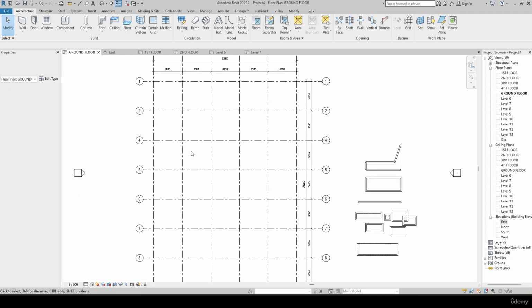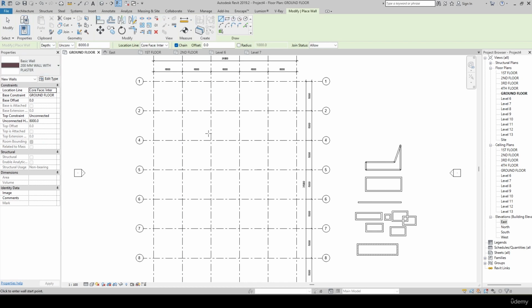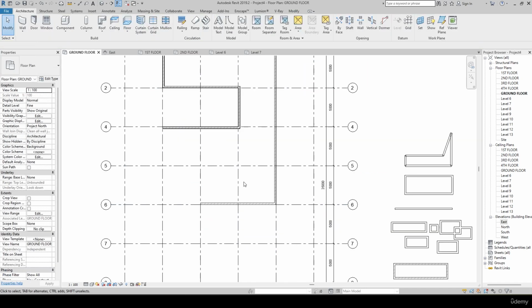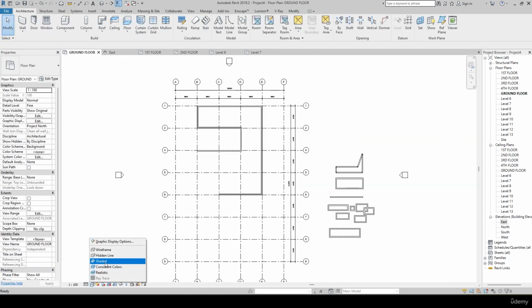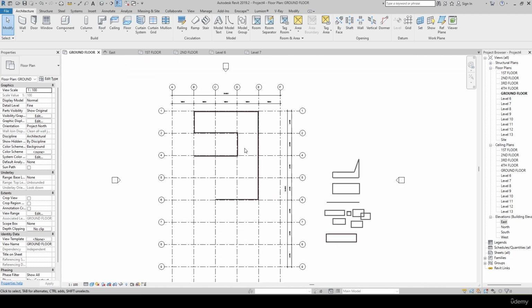This is how the grids are going to open, and you can simply take the walls here, or maybe I'll select the finish face exterior. Select this way, you can close, you can take again. If you wish, you can take this way, right? Whichever direction you want, you can add the walls and you can add the columns, right? And if you want to see it realistic, you can show it shaded, right? See, this is how you can create the drawings.